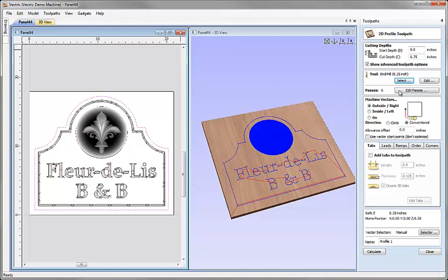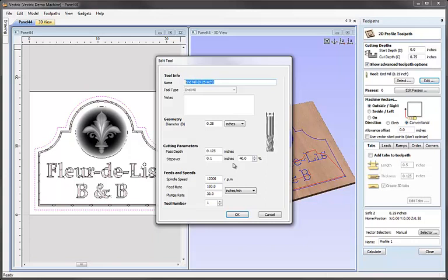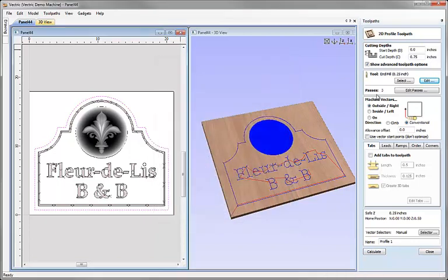So there we've got our 0.25 inch end mill, and in this case I might want to override some of the parameters for that tool. I'm going to hit edit and change the pass depth for that tool to be 0.25 of an inch. I'm confident that I'm cutting soft enough material, for example, that I can be a bit more aggressive with that pass depth. And when we hit OK, you should see the number of passes we're going to take reduced by half. So if I hit OK, you can see that's updated, and now it's only going to need to go around that 3 times, cutting 1/4 of an inch deep on each pass in order to get through the full 3/4 of an inch of depth of material.